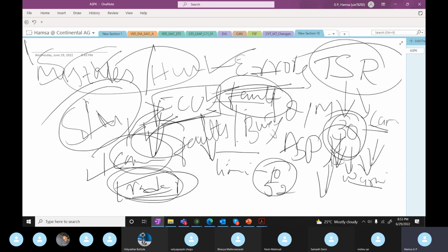That's how the serviceman will understand that the ECU was not getting the input from the camera. Otherwise, he cannot even get to know. This is called a fault, actually a communication fault. In faults also there are multiple types. This is one of the communication faults.